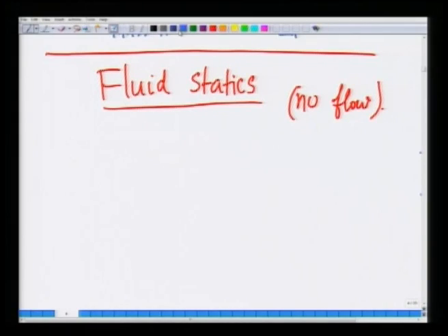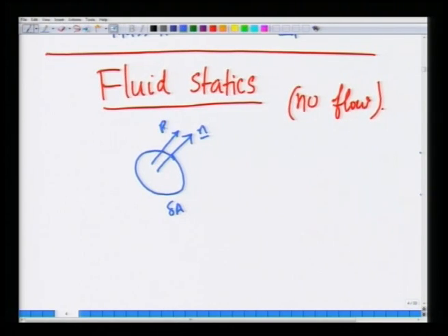You take a fluid volume, construct a surface. At any point in the volume, construct a surface of area delta A. This surface is denoted by unit normal n. So, in general the surface forces are in the direction of n, which is what I call R n, and in the direction perpendicular to n, which is what I call R T 1, the tangential forces. These are the shear forces.